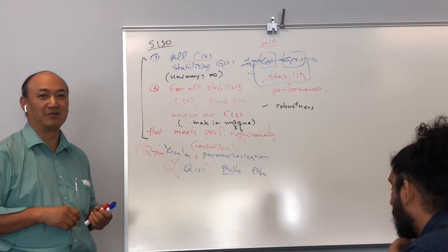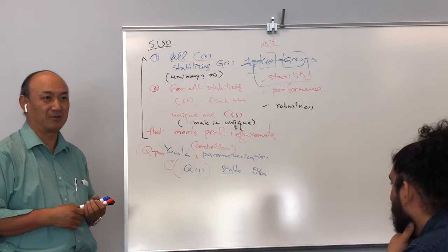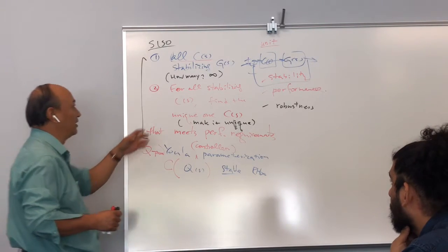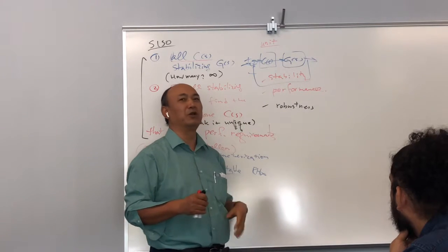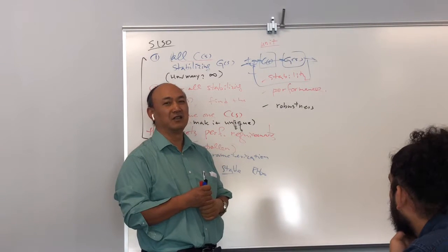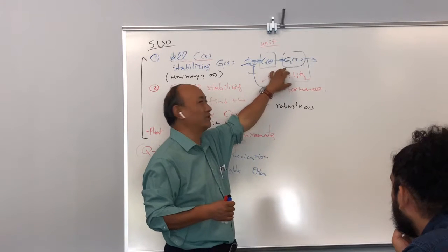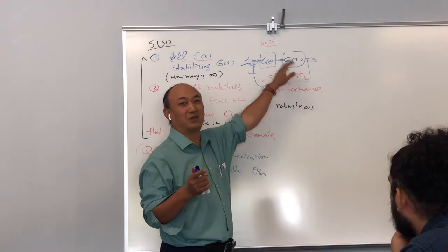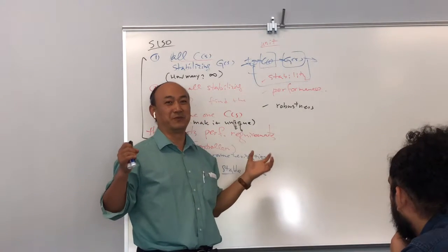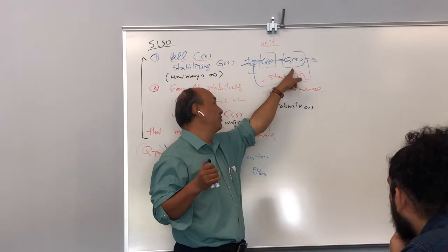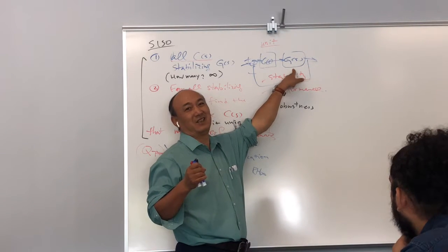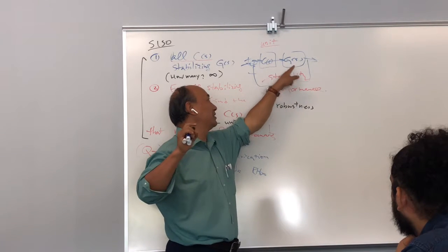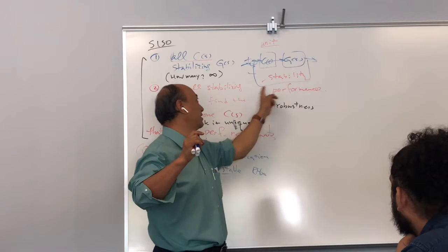Do you still remember this part? I usually give an oral exam to PhD students, so be careful, I'll ask you. Say I have an open-loop stable G. You find a controller to control this, but if the controller C is not chosen properly, you will make this system unstable, even though open loop it is stable. Make sense? But if you choose one that makes the open loop stable, the closed loop is also stable.